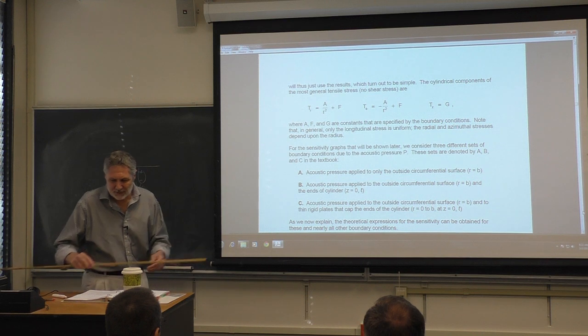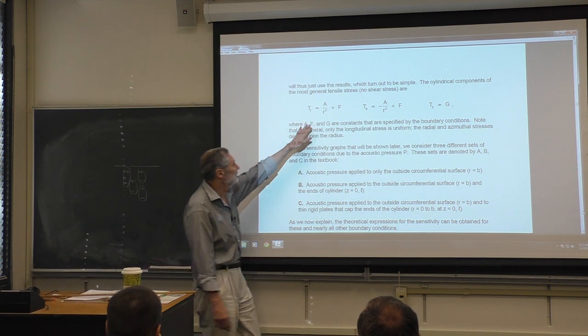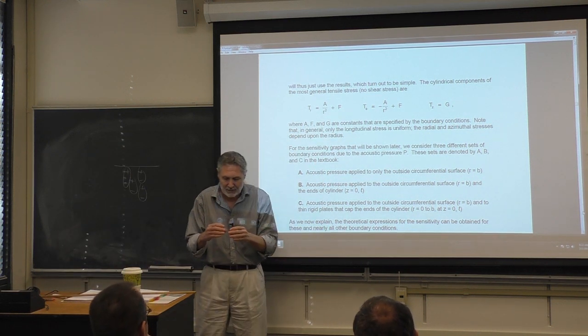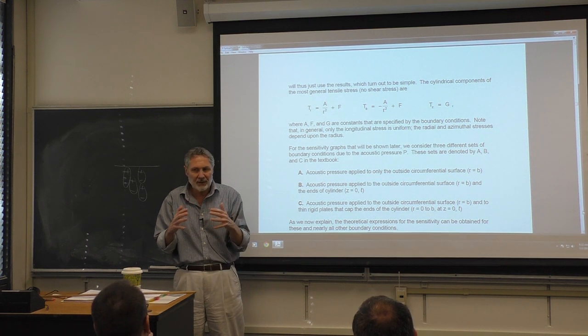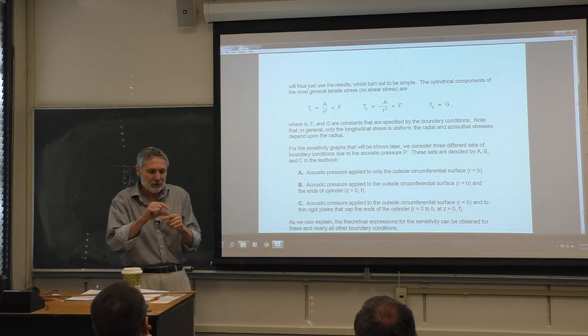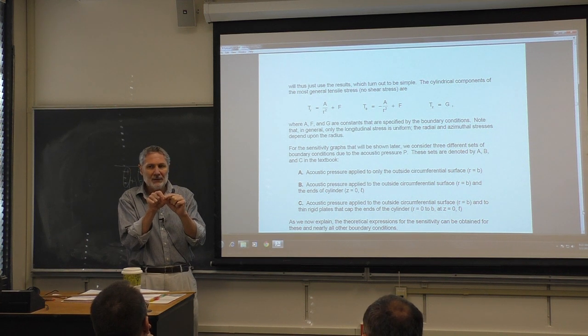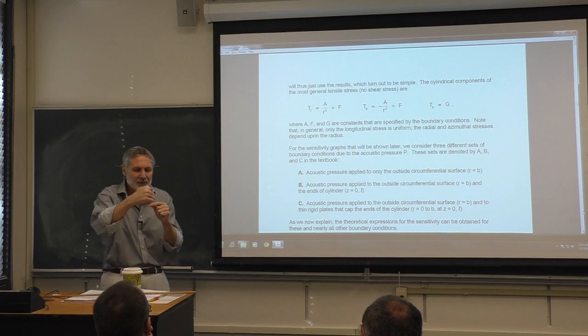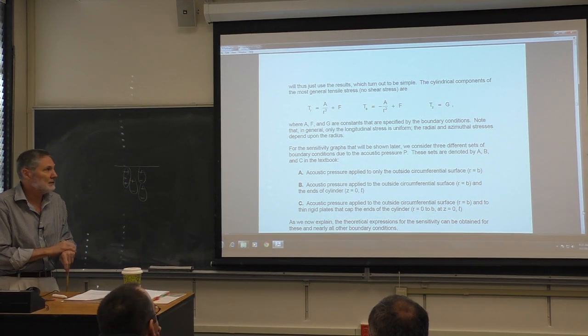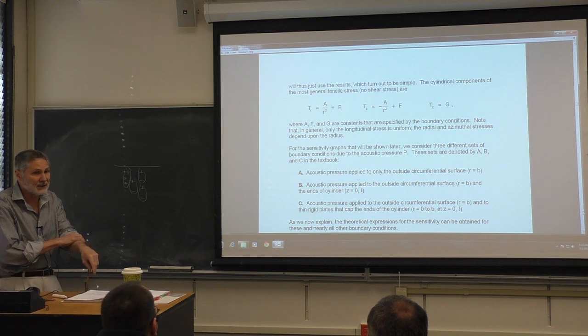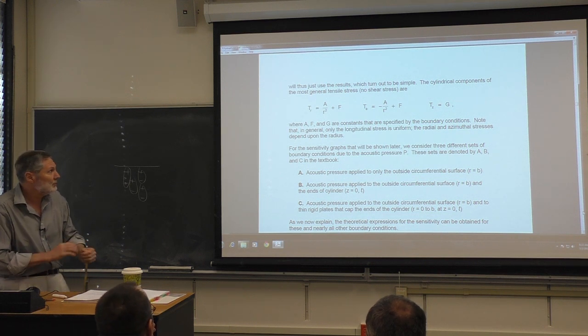Now, one way I was thinking about this, one way to appreciate the fact that there's radial dependence here is that because we're in the quasi-static limit, that's fine for us. If you look at an element of the solid, it has to be in essentially equilibrium, okay? So all these stresses need to add, and that's exactly true in the static case. It has to be in equilibrium.